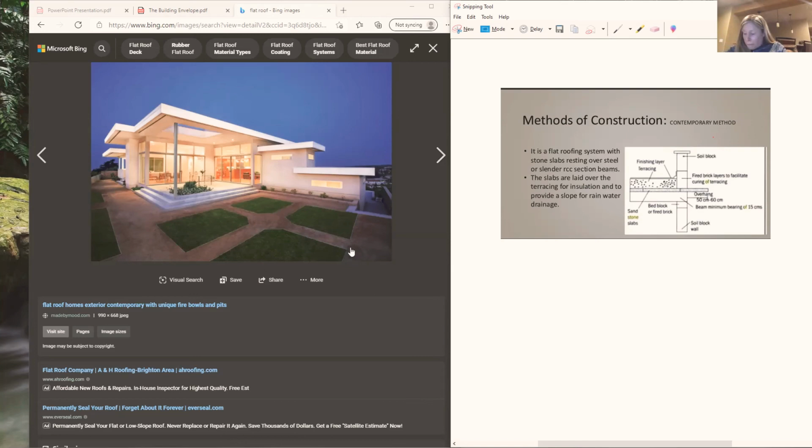Yeah, and we came up with one disadvantage, which is obviously snow. There is a drainage system, but in a climate like ours, it wouldn't do very well with all the load on a single flat roof. So it wouldn't be recommended as much in our climate. Yeah, it can't hold as much weight for sure. It's not as stable. There's hardly any room for insulation. I think that's a huge one, which is probably why they say mostly arid climates, I'm guessing.